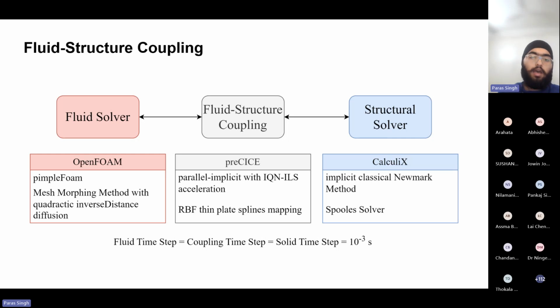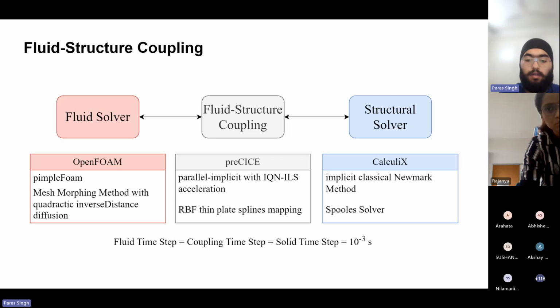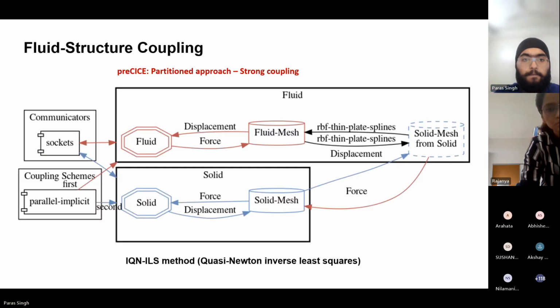For the coupling time step size, we have chosen 1e-3 seconds after ensuring time step independence and mesh independence tests.